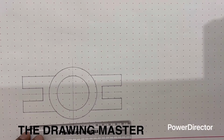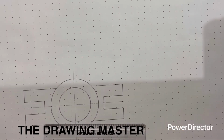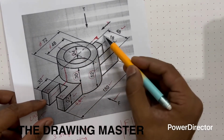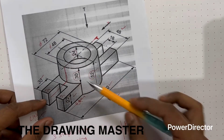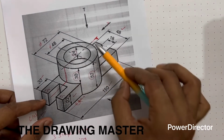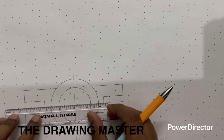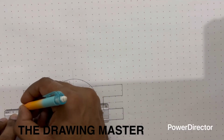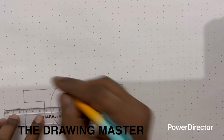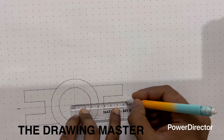This is the top view of the object. So now you have to draw the front view here, full sectional front view. For full sectional front view, we have seen this should be the cutting plane here. If this is the front view, the cutting plane should be here for sectional front. So let's draw this cutting plane in the top view. The cutting plane line should be a chain line thick at the end.